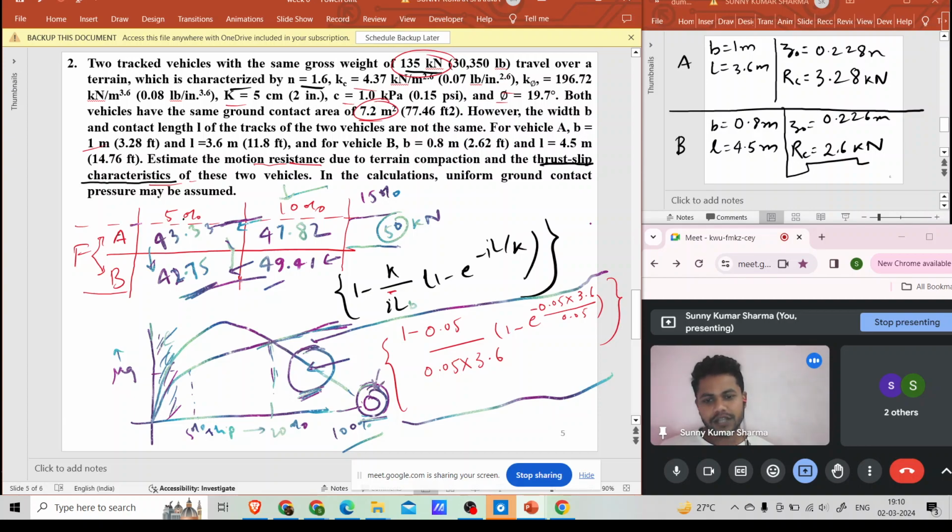So you have to give ballast to this wheel, and if you increase ballast so much that all the rolling resistance is overcome, you are starting pure rolling. You will not get any slip. If you don't get any slip, that is also a problem, and if you get a high slip, that is also a problem.